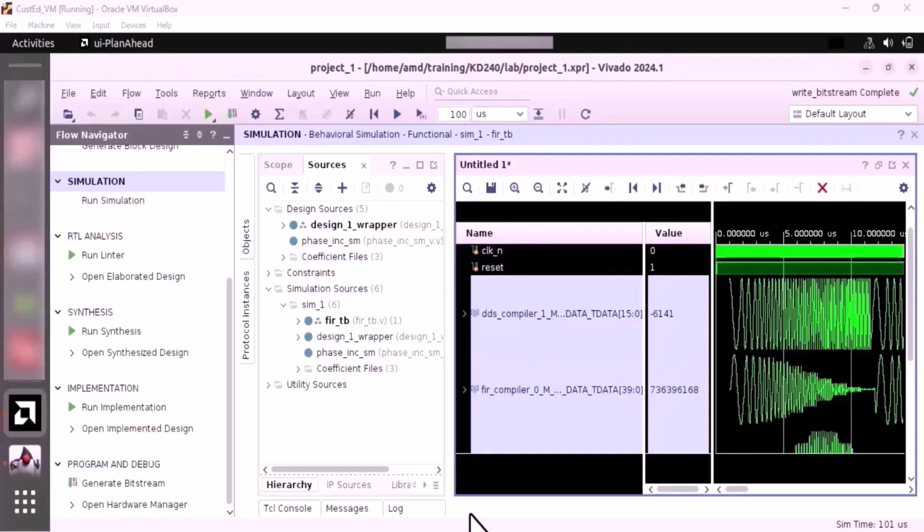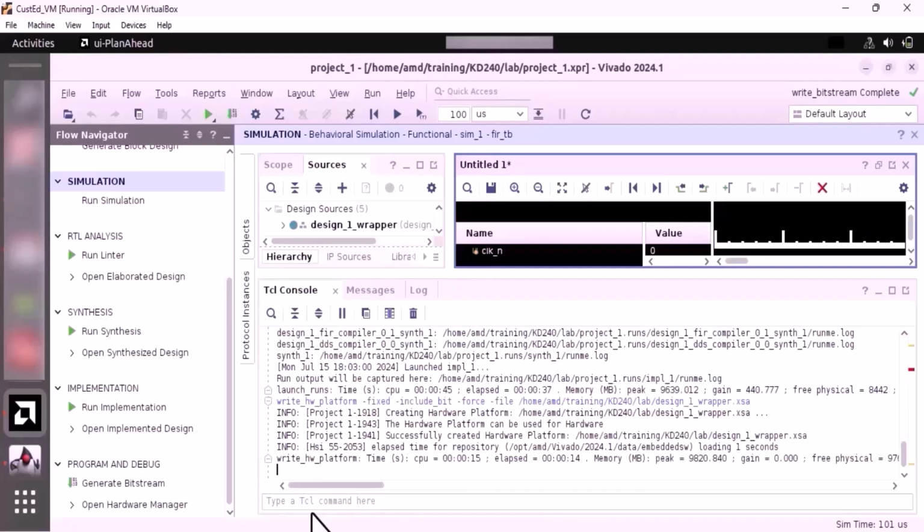Even though the design is purely RTL, the Zynq UltraScale Plus MPSoC processing system requires initialization and booting within FSBL and U-Boot before the programmable logic can access any clock to run. Hence, to achieve the minimum boot requirements, we will create a platform component based on the generated XSA and an application component on top of that in the Vitis Unified IDE. We will then program the PL with the bitstream so that the design will be running and the ILA can be accessed from the hardware manager in the Vivado IDE.